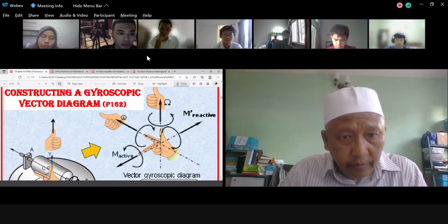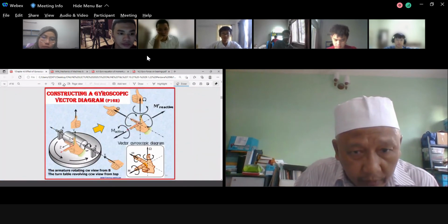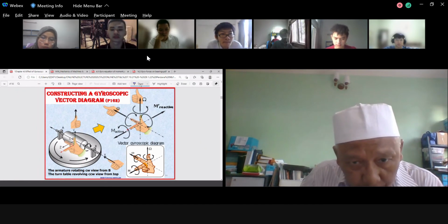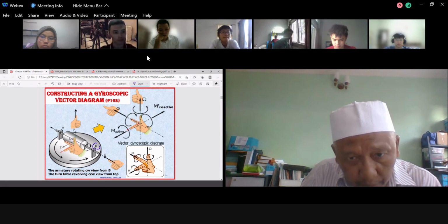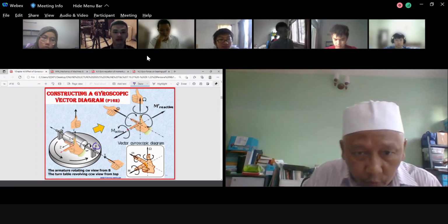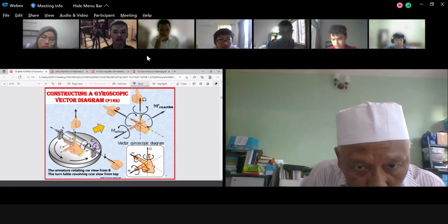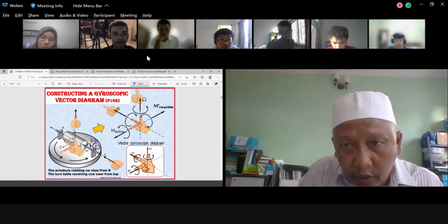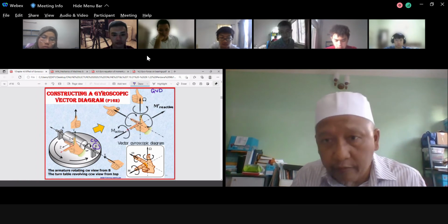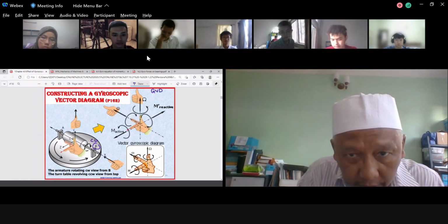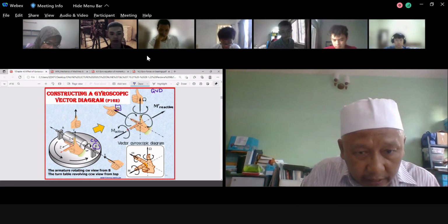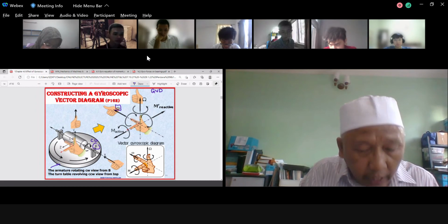So look at here. This one has been asked in the question to be viewed from B. Viewing from B, you find it rotating clockwise. Then you put on what we call the gyroscopic vector diagram. It is also mentioned that the turntable can revolve.